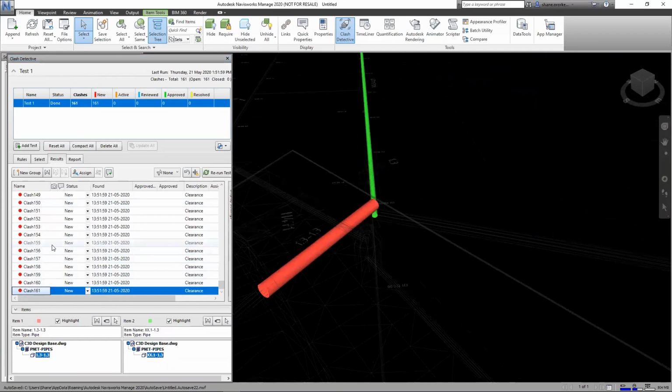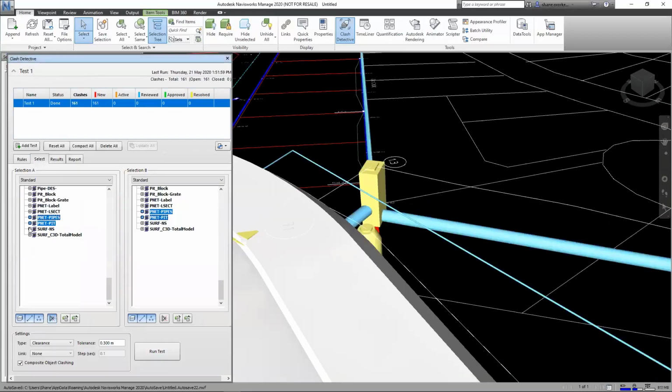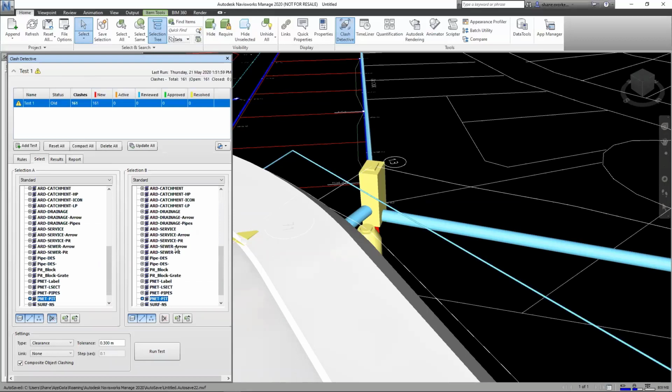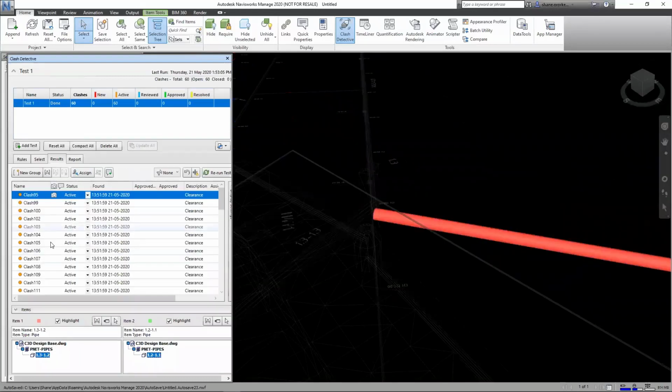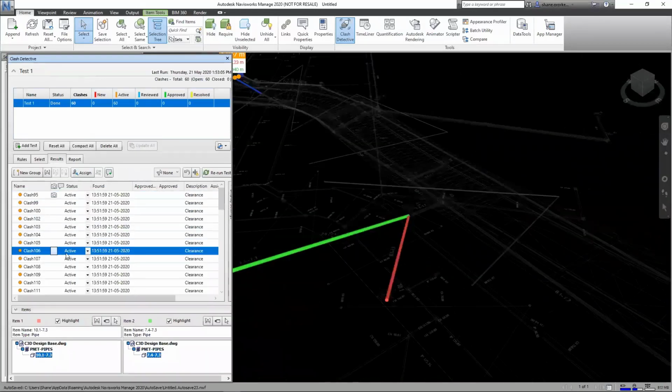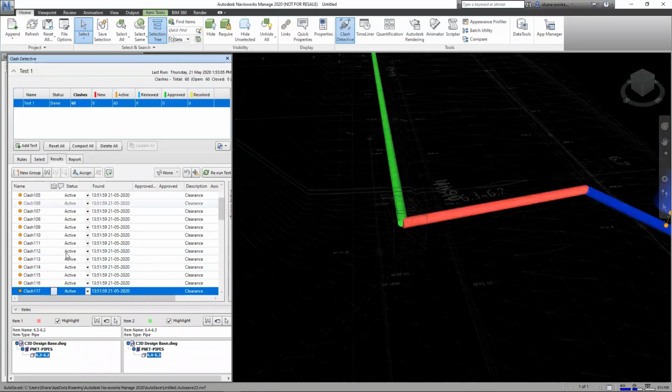So that's just a quick show of where pipe networks fit into a BIM workflow in Autodesk. One example is pushing them across to Navisworks. If you think about this test that I've run, I can actually compare any objects to any objects. So it doesn't have to be pits to pits. I could compare the pipes to the surface. Any of those tests I could make. So any selection of data, I can basically do that test on.